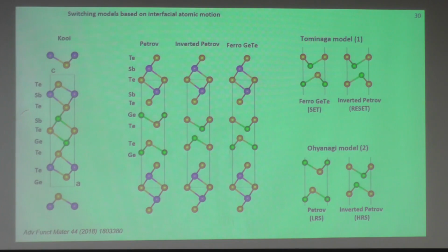You stack the superlattice layers with very thin thickness to achieve the composition of the GST 2-2-5 alloy. This brings the layer thicknesses to the range of 1 nanometer of germanium telluride and 1 or 2 nanometers of antimony telluride. So here we have 2 unit cells of germanium telluride and 2 unit cells of antimony telluride.